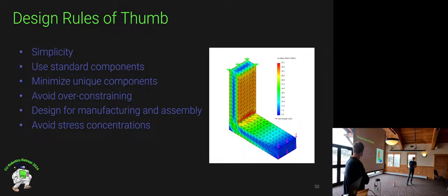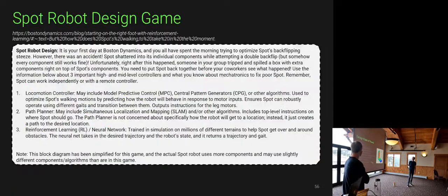Avoid stress concentration. This looks like SolidWorks. This is a simulation you could do with SolidWorks in like 5 minutes, so it's pretty easy to use. You'd probably want to fillet this edge to avoid that stress concentration. Include redundancy. People were talking about that all the time yesterday. And I guess I included this one sort of twice, but it's very important: make sure you can screw in all your bolts and stuff like that.